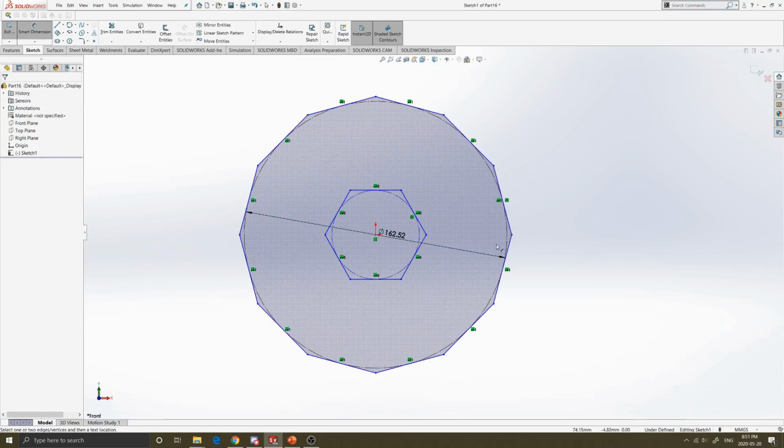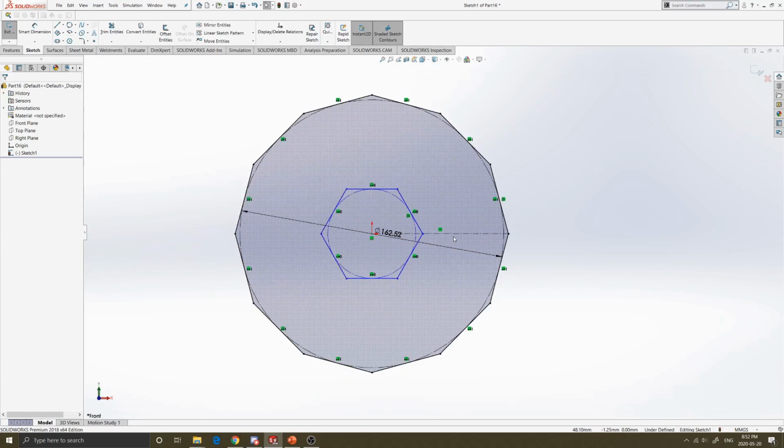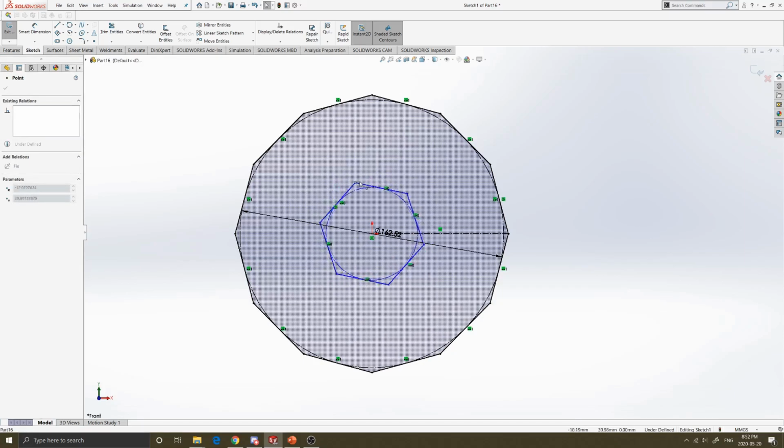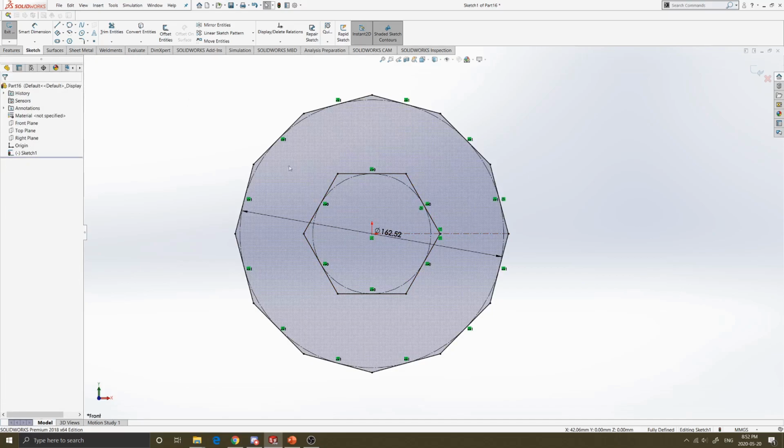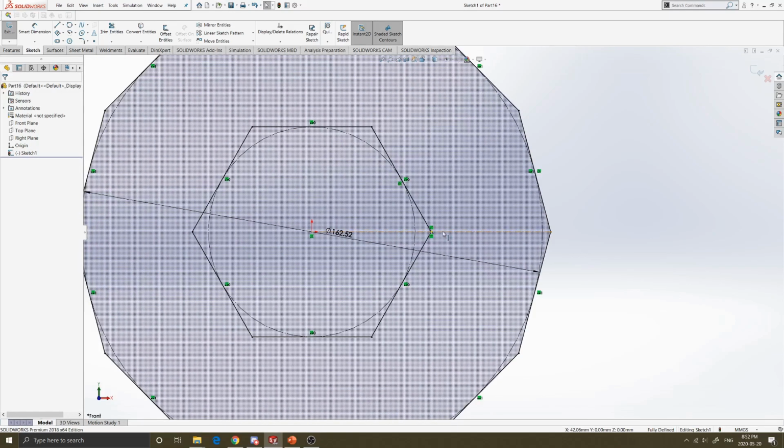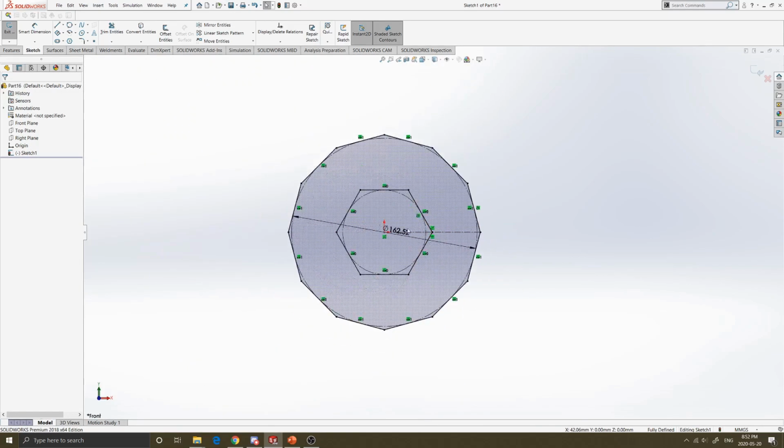Yeah, because before and the orientation, I believe. So let's say, yeah, this line is horizontal. The center line is horizontal. Therefore, this whole thing is defined. As you notice, it turned black. So black means it's fully defined. This center is not defined though, because as you look, you can make it bigger and you can rotate it. So if I were to put it on here, oh, I put it at the center point of this line, which happened to, so it's fully defined now.